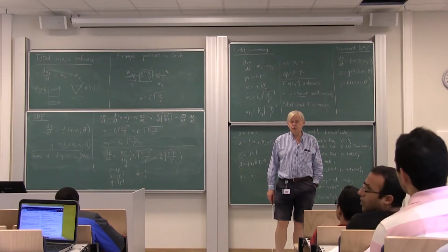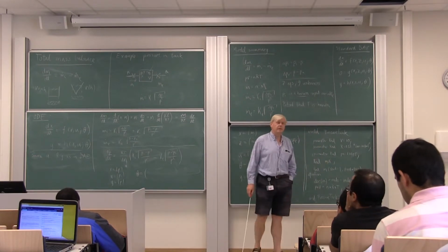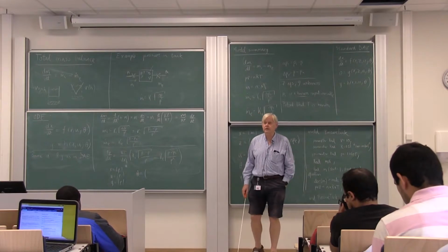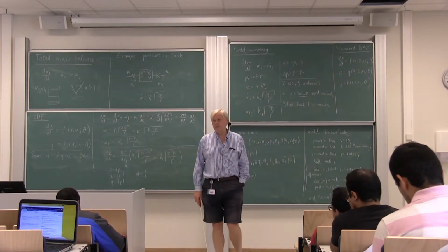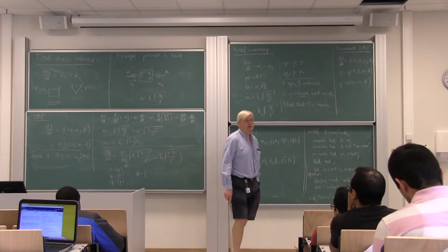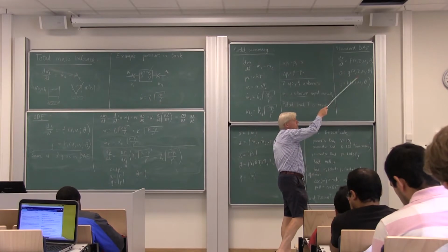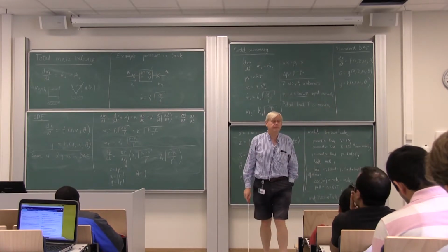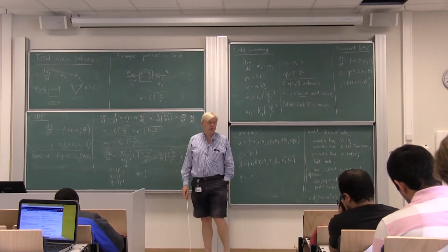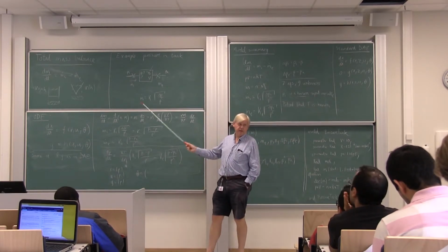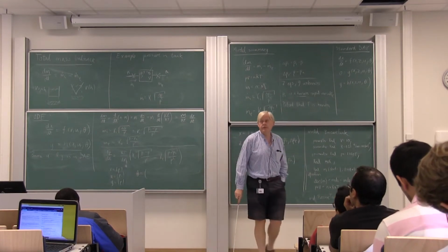And in this newer version of the course, I have decided that since we have DAE solvers like Modelica, OpenModelica, let's put less emphasis on this manipulation and more emphasis on formulating the models. So because of that, I will emphasize developing DAE models. But of course, you also have to know or understand how to change it to ODEs in case you want to simulate it using Python, for example.